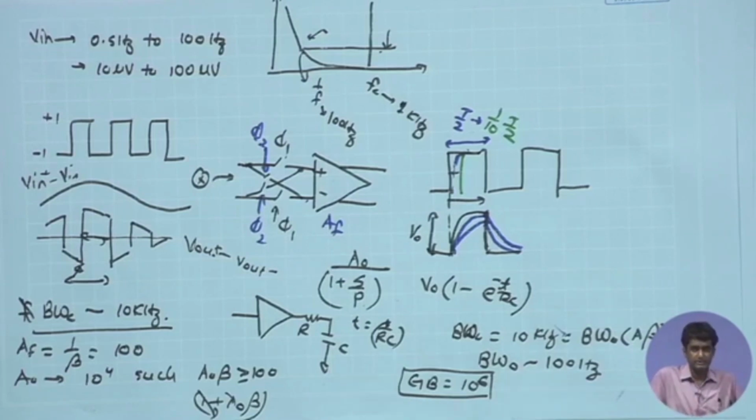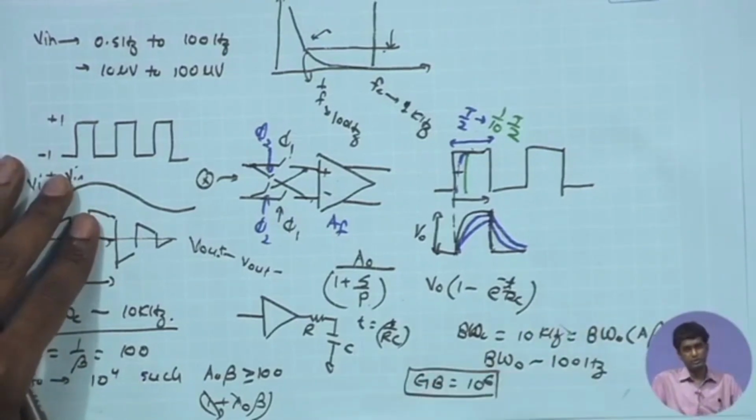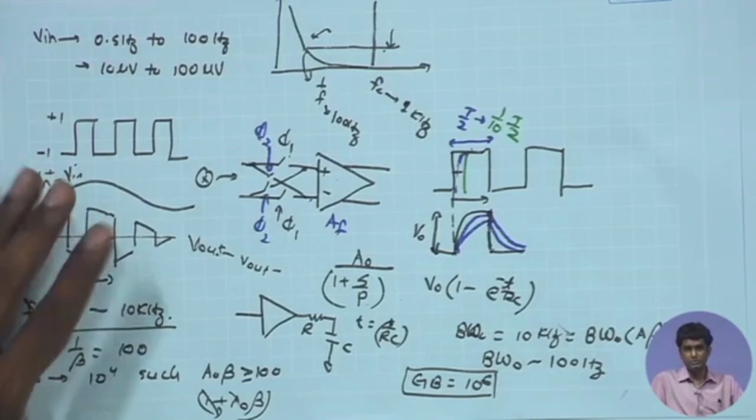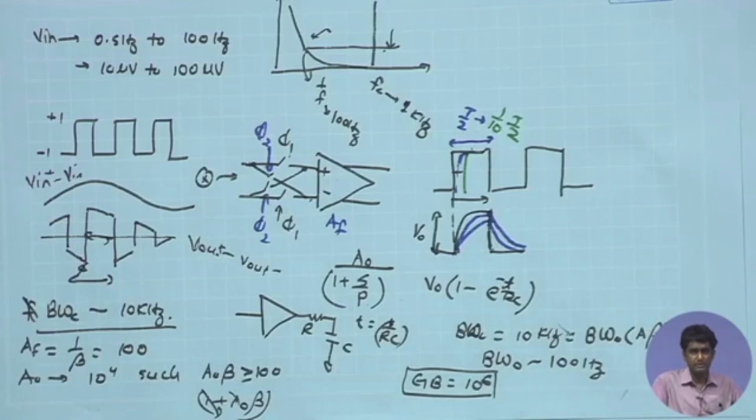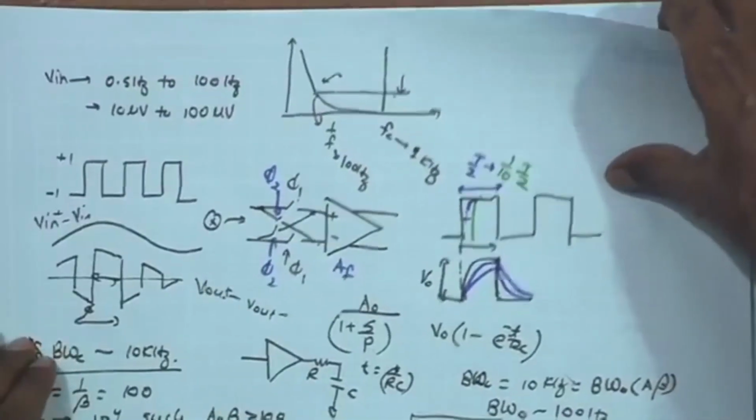So the gain bandwidth product is an important feature of the overall open loop amplifier with which we can begin the design. And now, while looking at the design, we have to recall how the gain bandwidth product depends upon the circuit parameters of, say, the 2-stage op amp, and from there we can proceed step by step and look at the other parameters like the overall bandwidth and the signal swings, and include them step by step. Also, looking at the interface of the circuit with the next stage and the previous stage, we have to estimate the value of the load capacitance, which is going to play a role in determining the compensation capacitance values.